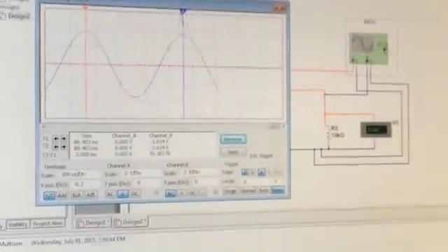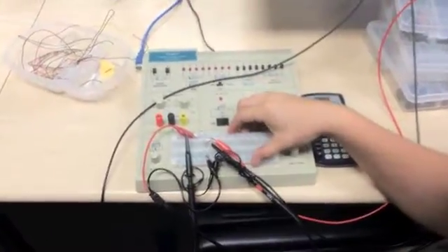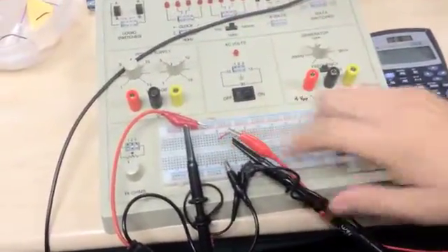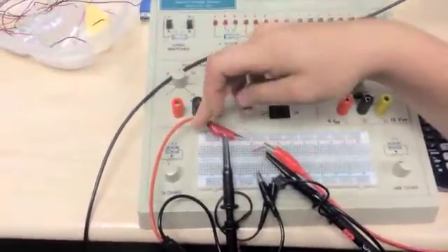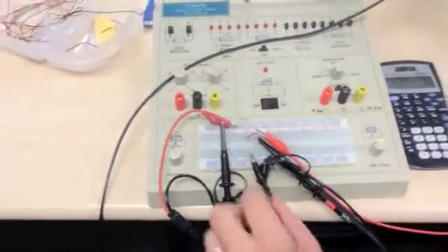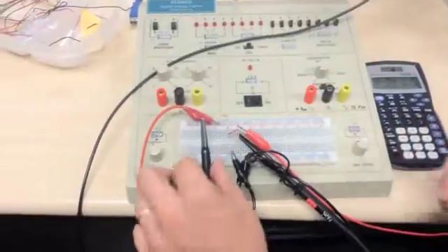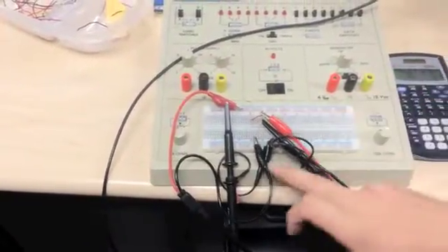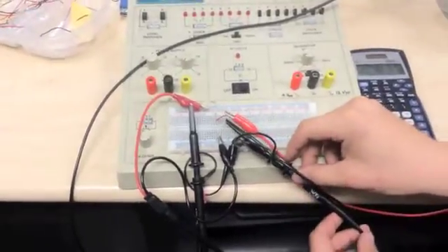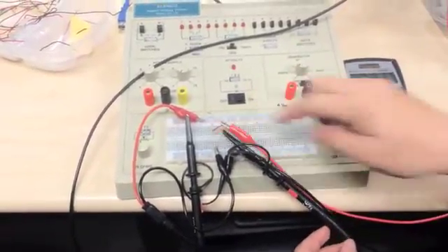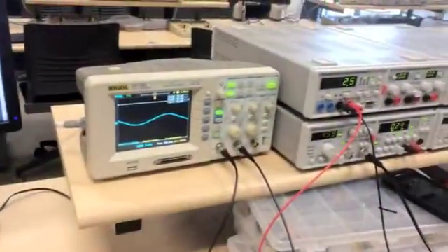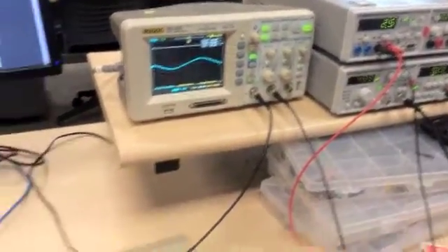input sources. We've set up the same circuit here on the board. We have a 3.3k ohm resistor here, a 10k ohm resistor. Our function generator is set up across the positive rail and going to ground. Also, we have channel A here for the oscilloscope going to the positive and to the ground. We have channel B hooked up across resistor 2, which is the 10k ohm. And our multimeter is also set up for R2. We just used a wire for proxy. It's also connected to the same common ground.